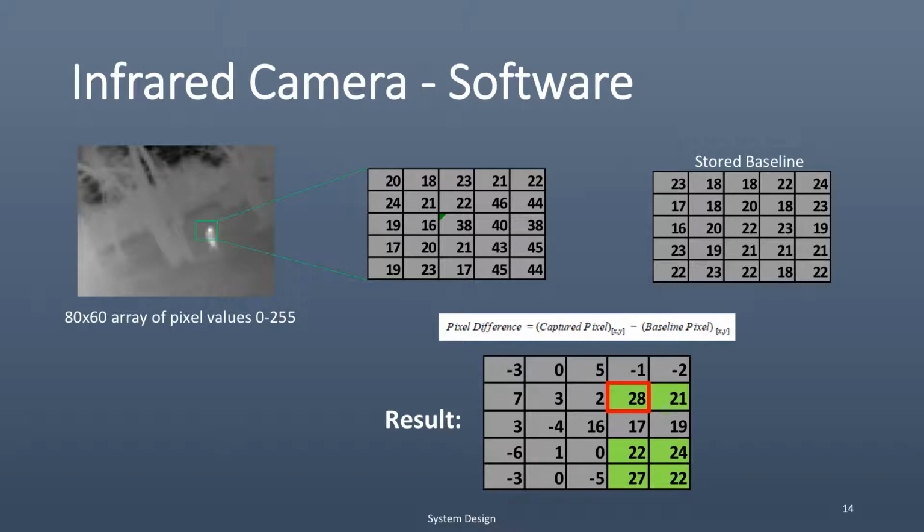Before the new baseline scene is calculated, we compare the recently captured image with that baseline, as seen here with an example result. These pixels are then looking for a delta of 20 value over the baseline scene, which equates to approximately 11.7 degrees Celsius. And then the largest of those deltas is used for the center of the image when it comes to drawing boxes, which we'll see later around the object.